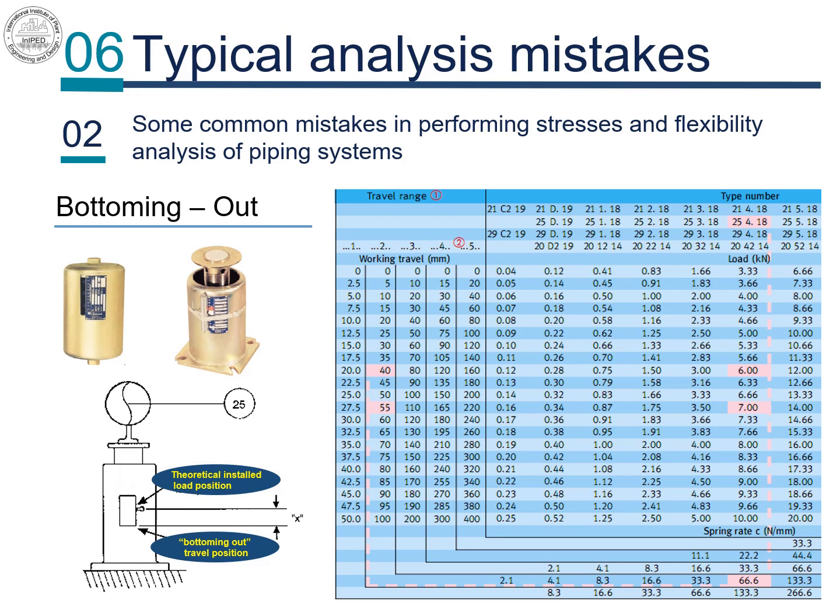When the pipe is in operating situation, it will move down according to the analysis, by 15 mm, and the spring will be further compressed, to 7 kN. On the spring travel scale, this will be at the travel position of 55 mm from zero. We see on the working travel range that the selected spring will have another 45 mm of travel, which is actually a safety margin, before it reaches 100 mm of travel and bottoming out. So the total travel before bottoming out from installed position will be 60 mm. The pipe stress analyst should ensure that in all operating regimes, pipe travel with this spring will never exceed this distance.